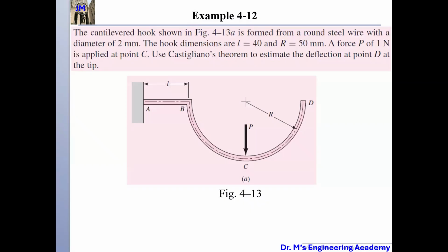Because, as I said, a concentrated force is always a troublemaker, right? Whenever you see a concentrated force, you always divide the structure at this given point, because you are going to write something different for this part and for that part. Make sense? Whenever you see a concentrated force, you must divide the structure at the point where you apply the concentrated force. Okay? No question? But let's look at this.